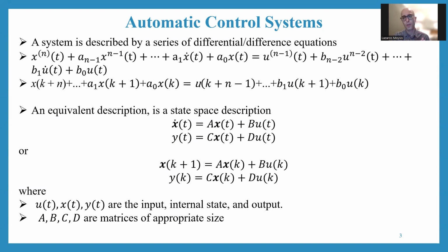I'm going to discuss this analytically in another video, but the idea behind a state-based description is this. Say you have a differential equation of higher order that describes a phenomenon. Let's say it's a second order differential equation or third order or maybe more, right? The idea here, and this idea was proposed by Kalman, which we discussed previously, is to use a set of first order differential equations to describe this phenomenon. And it is an equivalent set, so we don't lose any information. We just transition from a higher order differential equation to a specific number of differential equations of first order,